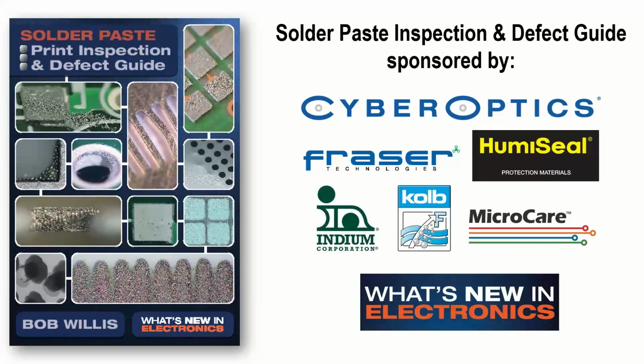Okay. Yes, the gentleman just saying about with regard to maintenance of the machine. One of the key things with maintenance of a stencil cleaner is filtration. It's the filtration of the metal bits. And if you think about solder paste, it's quite expensive stuff. There's a lot of metal there, so I certainly wouldn't throw it away. I'd certainly look for some way of recycling it through a recycling agent, again with your solder paste. So the filtering and getting rid of the particles is something you need to consider, because that does impact the maintenance.